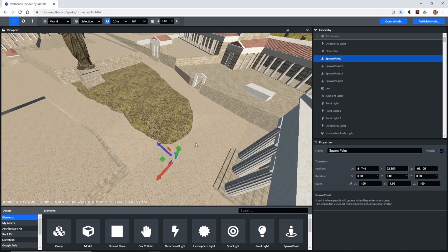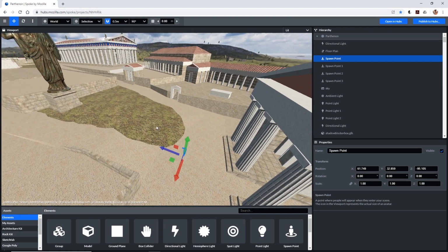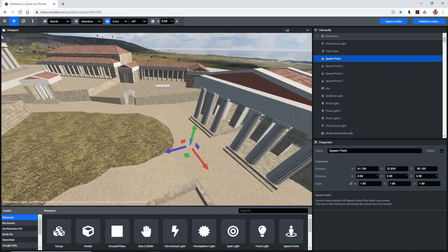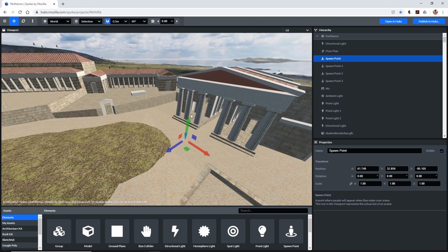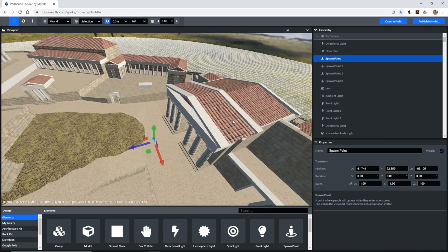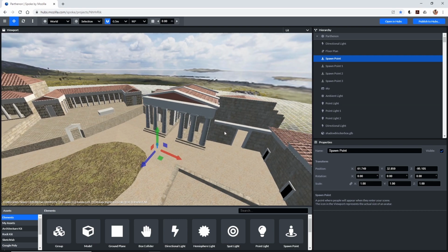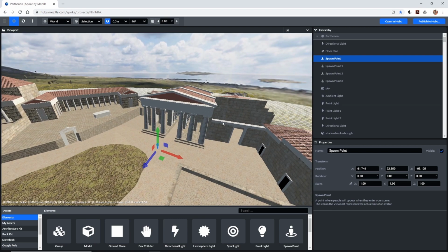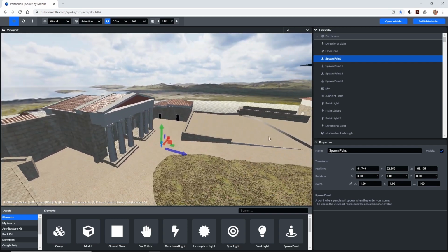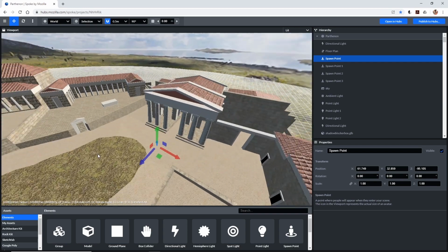They could fly too, but if you want to force them to walk, because they'll end up being in VR and teleporting, you need a collision mesh so that you can tell them how to collide with this world. The trick is you don't want to make every object you import collidable, because here we have a roof and we may not want to be able to land on that roof. We may want to limit them to being able to walk in specific places while still being able to see the more detailed objects in the scene.